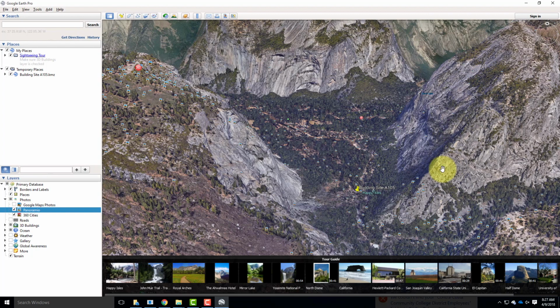We're not going to have a huge amount of light because of the 2 mountains on either side of our building site. So as the sun swings around, we're going to get sun in the middle of the day, but we're going to have early sunset, so to speak, because it's going to go behind this mountain. And we'll have late sunrise because it's coming up behind this mountain. In terms of wind, there's a pretty good chance that there'll be a down canyon wind early in the morning and then an up canyon wind later in the day, just in terms of thinking of general site conditions.